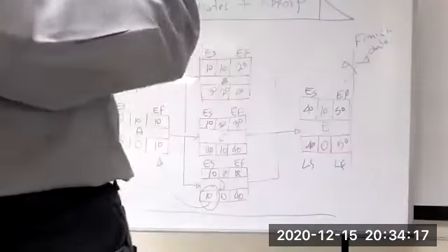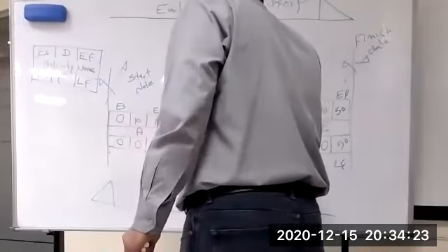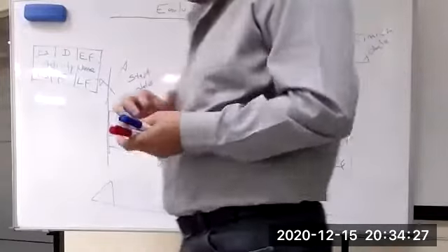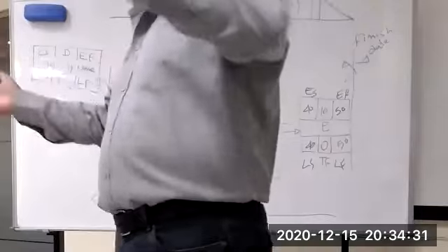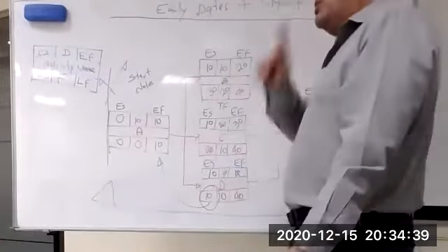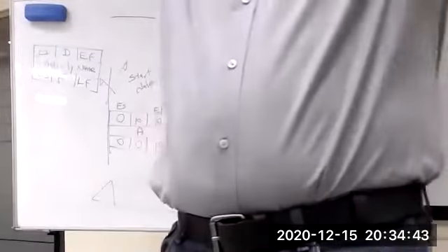We have something else, we call it float, free float. What is a free float? All of this float is total float. Free float is between predecessors and successors. Predecessors and successors mean what? It will impact the successors only. Free float will not impact the entire project.